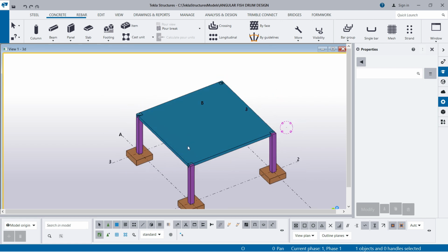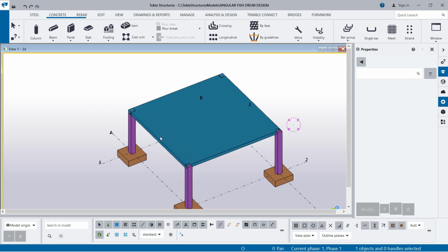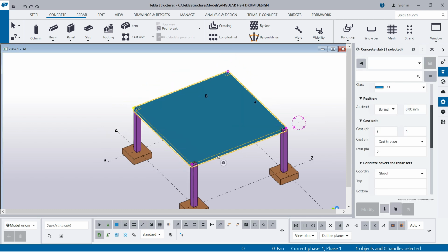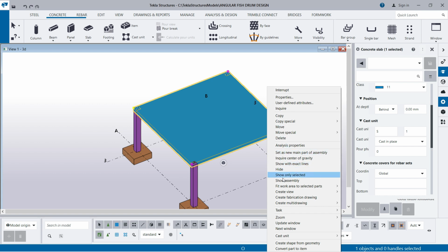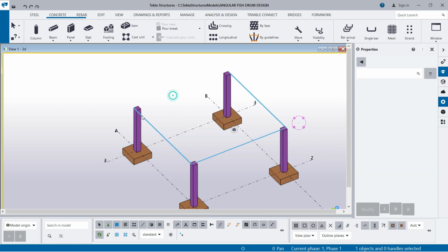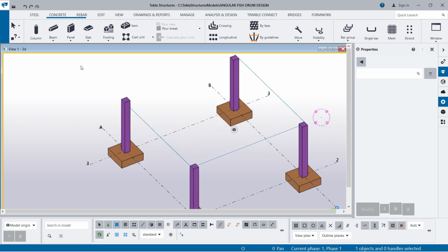The next structural element is the wall that you're going to be placing on this successfully. So for us to place the wall effectively on the top of these columns, we will need to hide this reinforced concrete slab. So I will select that, right click, and then I use hide options right here. So I have this. You can see I still have a line all around, but if you really want to see the line before you hide, you need to hold the shift key. So this line will be hidden. All right. Okay, so we make progress.